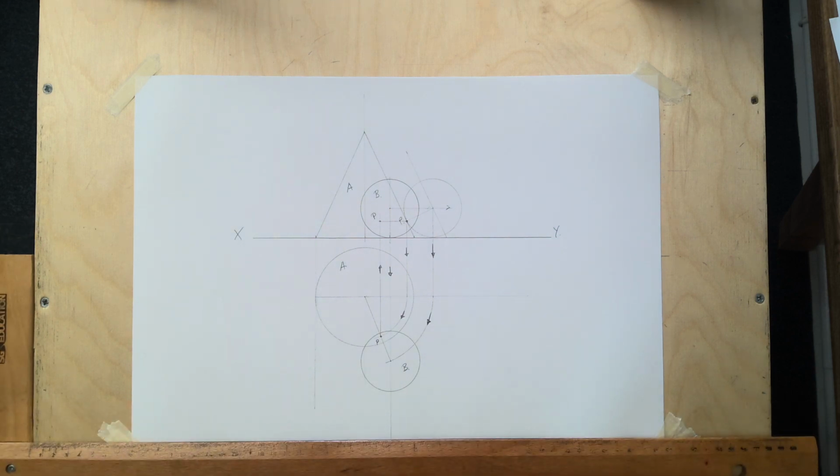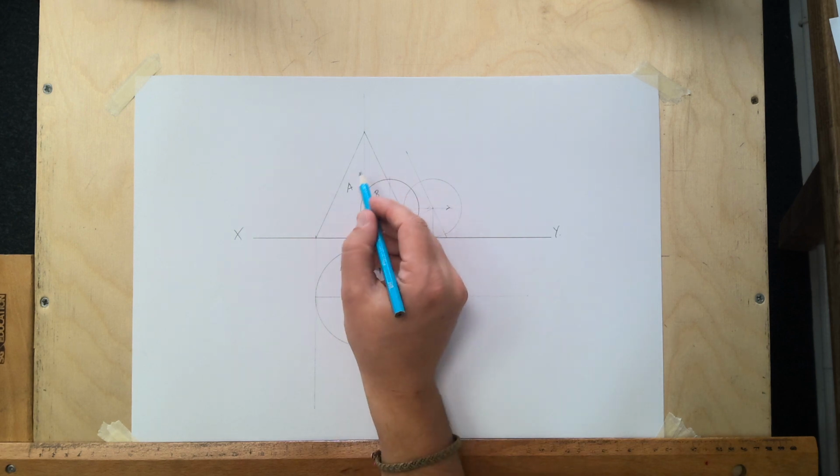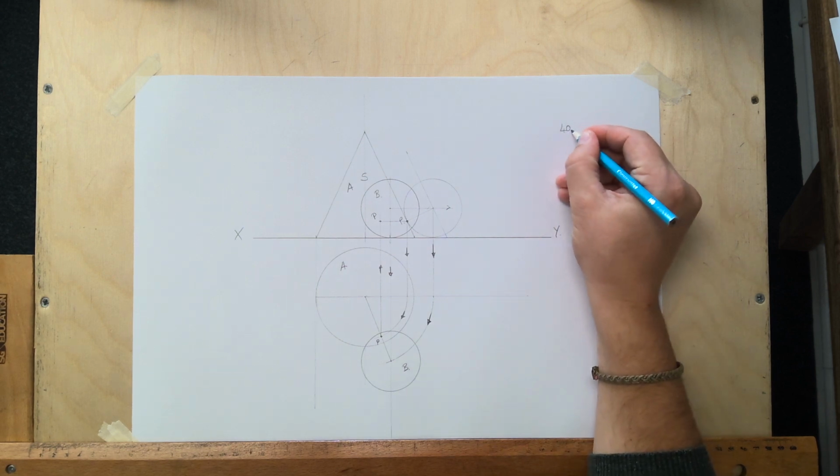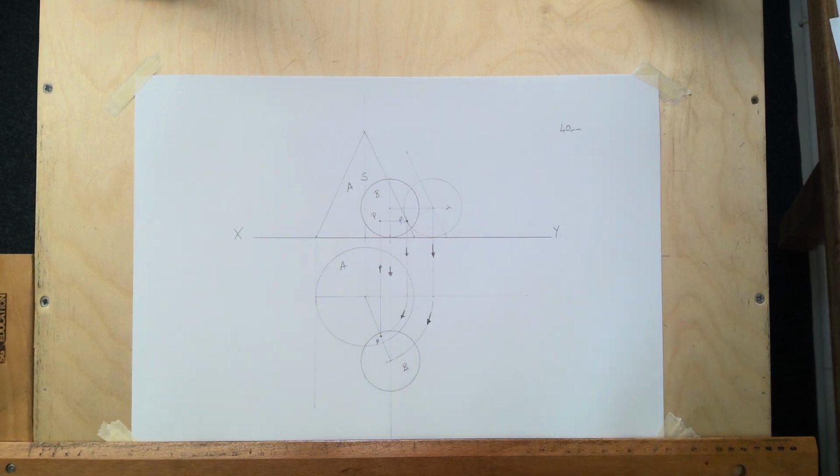Now, that's the first part, so draw the elevation. Now the second one: draw the projections of another sphere C of 40 millimeters diameter, which is in contact with the sphere and the cone in position S. So the image has a position S to be here. Somewhere we're going to have another sphere in there, and it tells us it's 40 millimeters. And the center of the sphere is to be 50 millimeters off the ground.